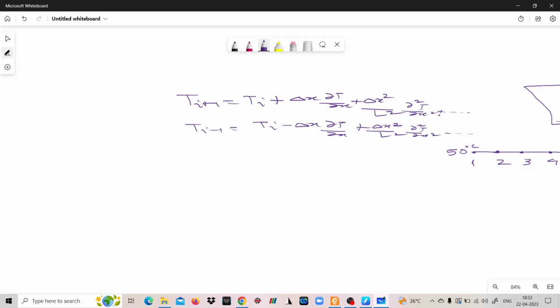Now here we'd like to preserve this ∂²T/∂x² term. Okay, so if you'd like to preserve this, you simply add T_{i+1} with T_{i-1}, so you will get twice T_i.